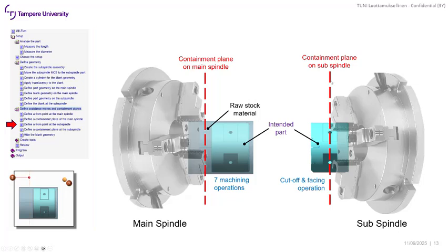And you can pay attention to the containment plate plane positions. One of them is 5 millimeter after the intended final surface on the left side of the component. And then the other containment, for the ease of assembly, we are defining the center point of this hole as a maximum zone that the cutter is allowed to go without collision with this window.